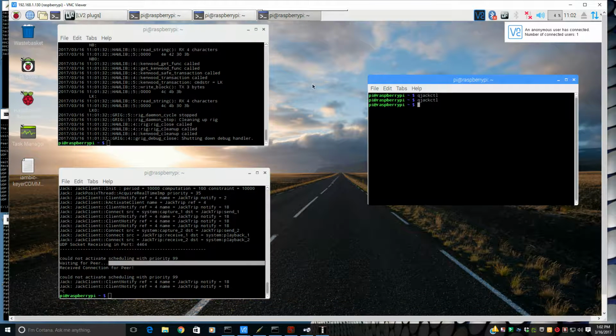On the Raspberry Pi, we have it interfaced with the K3S using the K3S's USB sound card serial port adapter on the back plate. So I have a USB cable running from the Pi over to the back of the K3S, plugging into the USB port back there. So you can send some commands to control things, and you can get the audio from the K3 HF receive and the K3 side tone if you wanted to listen to the side tone.